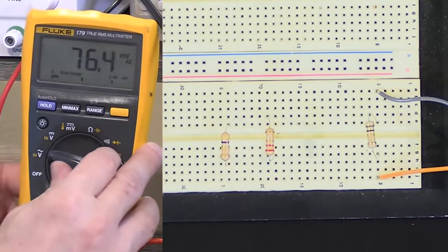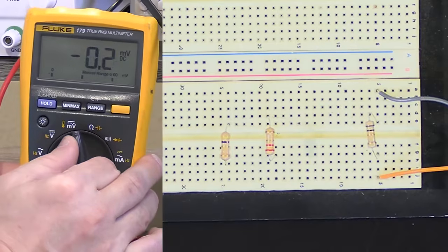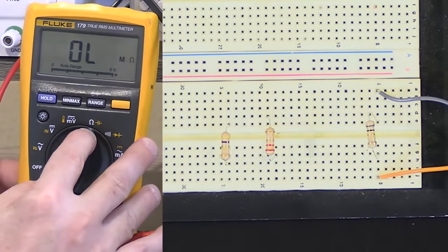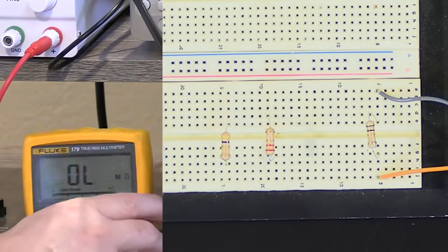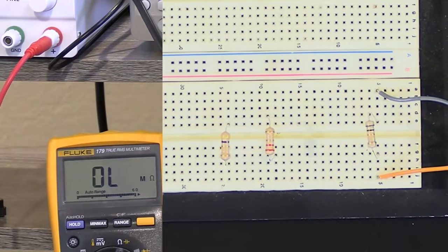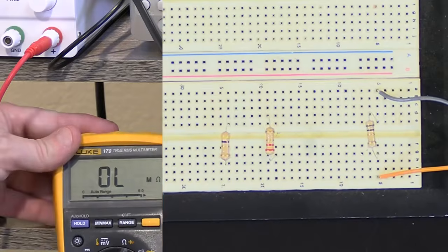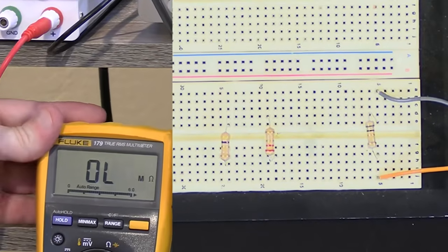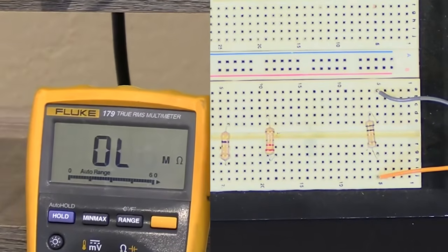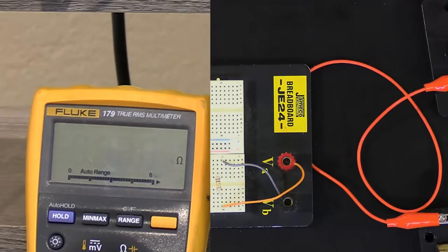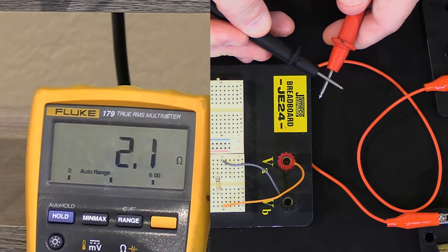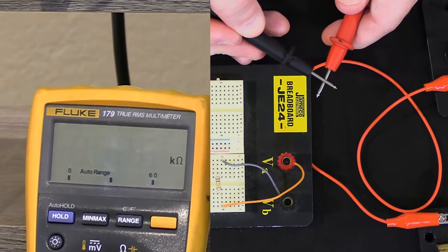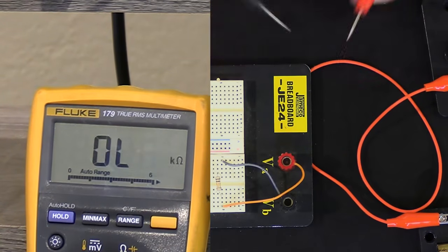All I'm going to do is turn this voltmeter. Let me see if I can get it where you can see it. I'm going to turn this voltmeter to the ohm position. I'm going to put it right back down here so the camera can see it. And hopefully, I can move these wires out of the way. You will be able to read that. And right now it's measuring nothing. If I touch the two leads together, it's not measuring any resistance. You can see on that display it's bouncing between 0 and very, very low.